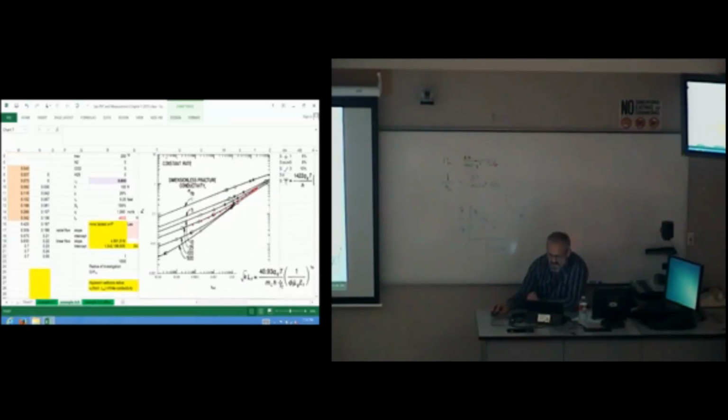The type curve is telling me which data to use. Now, I couldn't even make this type curve until I did my specialized analysis, got a square root of kxf, plugged in my 0.1 and got an x sub f, and then I could calculate t sub dxf. I couldn't even get on this plot until I was done. So now we're cycling through and correcting. And this is why we use the type curve. Just like I said earlier, sometimes it's the only thing we got because we don't have a specialized plot. But in this case, we're going to use it to recheck our data.